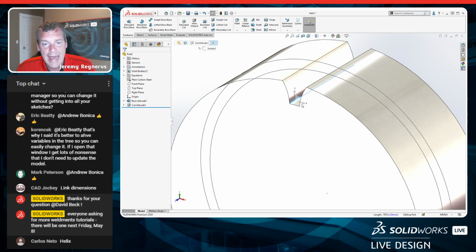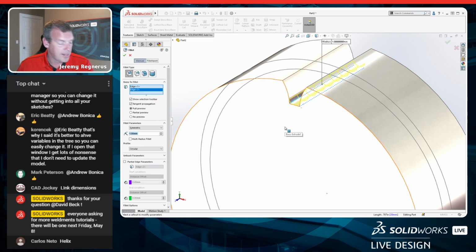We're going to add a fillet to these bottom 2 edges. Now, the fillet on the bottom of this is 30% of the module value. So anywhere you see that you can enter a number over here in the property manager, again, you can type the equals key, and we want to do 0.3 times, just like before, the module value. When I press OK, when a feature is driven by an equation, you'll see that we get the equation symbol in the feature manager tree. So we're starting to see equations are available anywhere you want them to be. So we're going to go ahead and press OK.